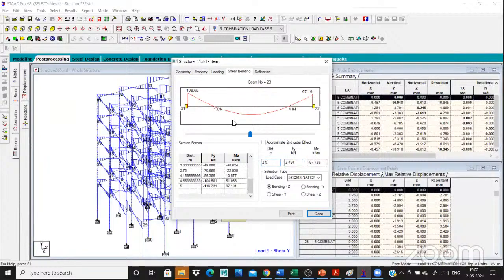2.5. You provide two cross sections. This is the minimum to group as one cross section, but this is 67, which is smaller, so you provide two cross sections. For shear also, the shear will be high in these two corners: 121.21, 161. The stirrup spacing will be less in this portion. In the mid portion you increase the height and the length of the stirrups, but at the two corners you reduce the stirrup length. Okay, this is the showing.